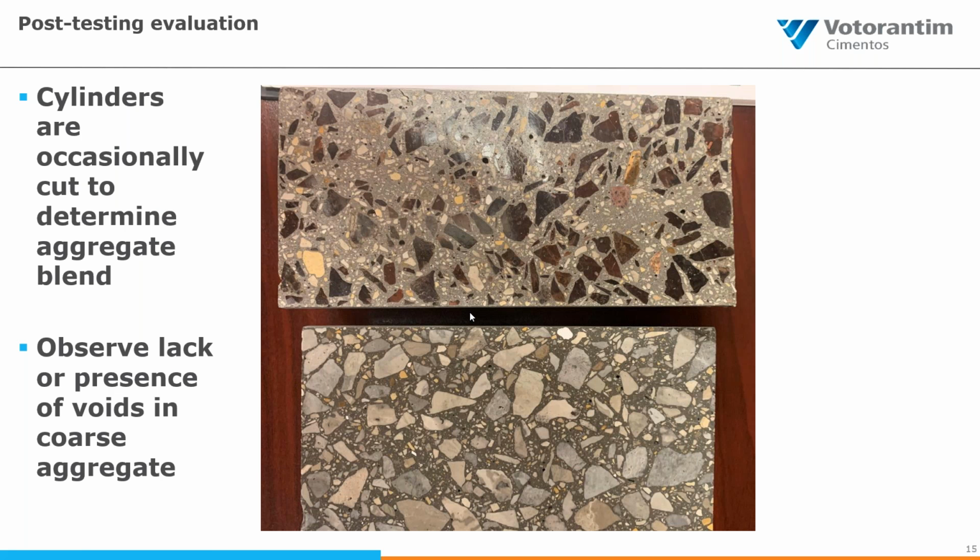It's not a very interesting test, although a lot hinges on it. So to go back to what I was discussing earlier, and what Lloyd talked about, a huge concern in the majority of modulus of elasticity, while some comes from overall paste strength, is where you're going to derive a lot of that value, which is from your aggregate. Chicago is a limestone dominated market. Most of our local materials are limestone.